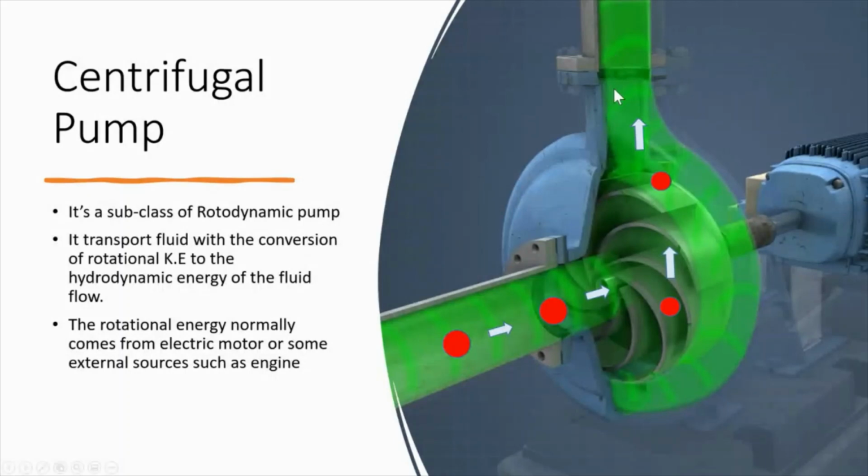Basically, the way it works is this: think of a liquid ball, or a particle in the liquid. Something has to push that particle into this central hub. The central hub is moving at a speed with kinetic energy. Then it takes that particle, puts that kinetic energy into it, and throws it out with that similar kinetic energy. No big pressure drop in here. Does it make sense? Any questions?